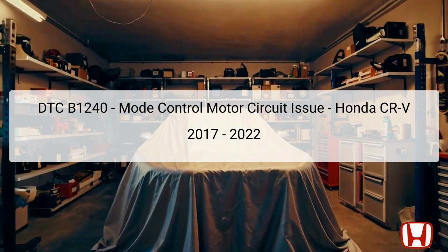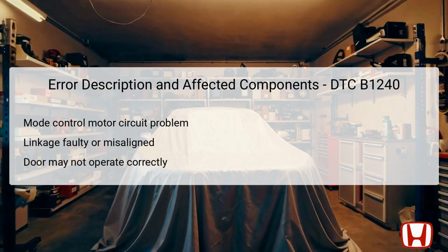DTC B1240 signifies an issue within the mode control motor circuit, which may include problems with the linkage or the motor itself. The mode control motor is a critical component that directs the climate-controlled air to various parts of the interior. This motor operates in conjunction with a series of linkages and doors that must move freely for optimal operation. If there's a malfunction in any part of this assembly, air may not flow as intended, resulting in inconsistent temperatures and comfort levels for passengers.